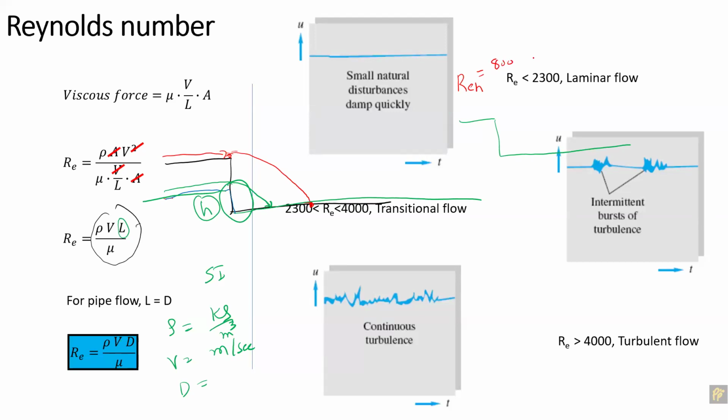And when the flow becomes turbulent, they also say we cannot run the simulation as two-dimensional, so we have to go for a 3D case, not a 100% 3D case, but with enough third dimension so that the flow can make vortices, and the vortices can cross and go in the third dimension. So let me show you one thing.